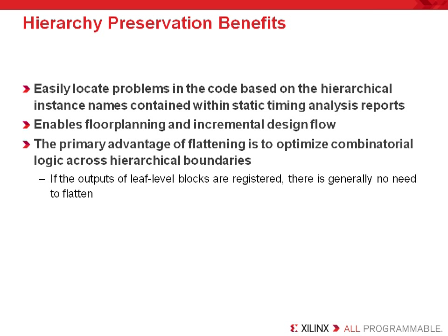Maintaining your design's hierarchical boundaries yields numerous benefits. As I mentioned a moment ago, it makes it easier to locate nodes when you are simulating, probing with ChipScope, for example, or simply reading a synthesis or timing report. However, what many customers don't realize is that it also enables floor planning and use of the incremental design flow. Incremental design allows users to maintain the place and route solution found for part of the design and only repeat place and route on components that failed to meet timing or have changed logically.